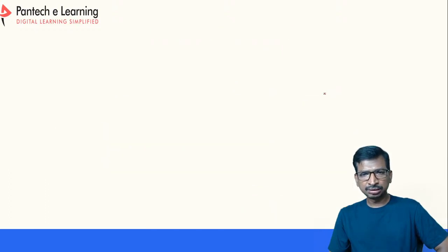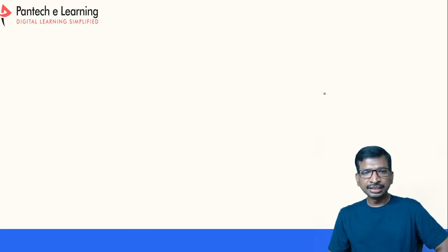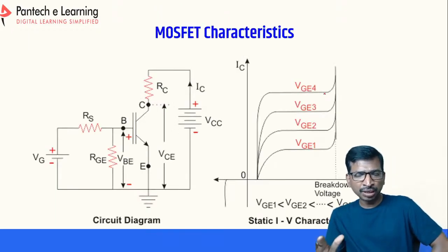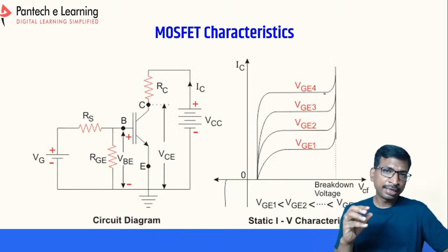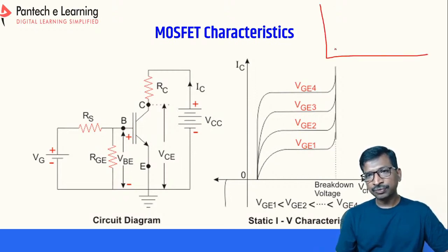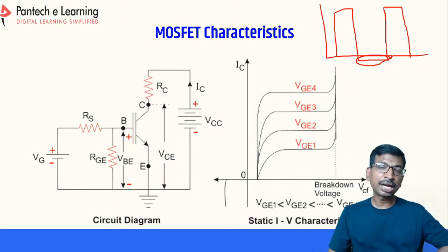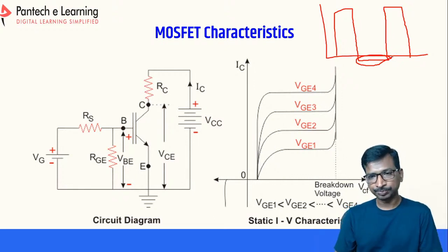And this is the IGBT also, the same procedure. For the IGBT at low frequency, there is no issue. Whereas if you are going for high frequency and high current applications, you have to introduce negative pulses also to turn off the MOSFETs. Instead of only square pulses, you have to keep negative pulses also. Due to this negative pulse, we can pull the MOSFET down to the off state very quickly for high power current handling circuits.